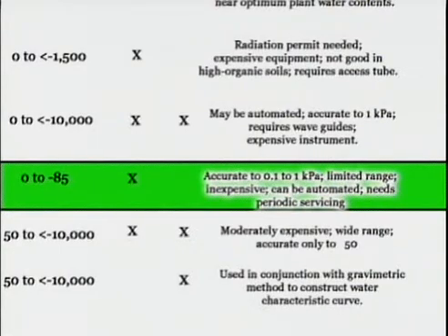They are quite commonly being utilized in the irrigation industry as a method of soil moisture monitoring by determining the tension with which the water is being held by the soil. Even though they're relatively inexpensive, the disadvantage is that you have to have a number of these stationed throughout the area that you want to monitor soil moisture on, because the portability of these is really not that great, in that they need a period of time in the soil in order to function.